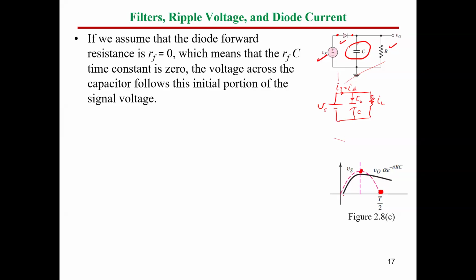So let's move step by step. Once the supply volt, this red color supply volt, is increasing and more than 0.7 volt, the turn on volt of the diode, the capacitor volt here will be nothing but Vs minus V diode. Assume that V diode is 0.7, so we can say V capacitor equals V source minus V gamma, or V turn on, which is 0.7 for instance. So this will be the shape now. The capacitor volt will increase until reaching the peak value.